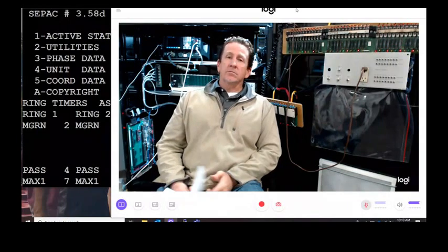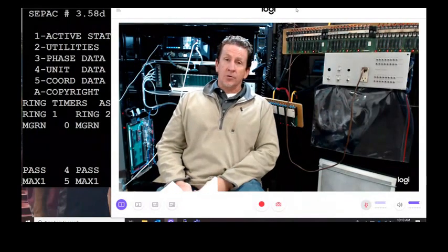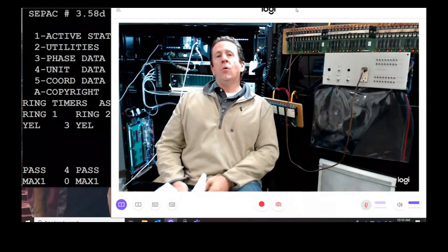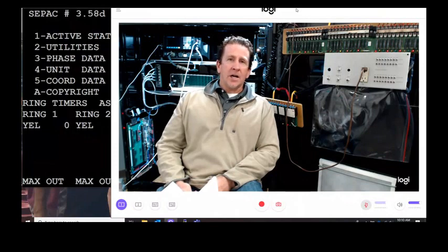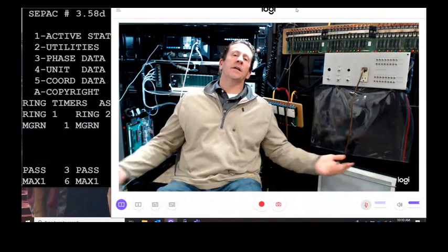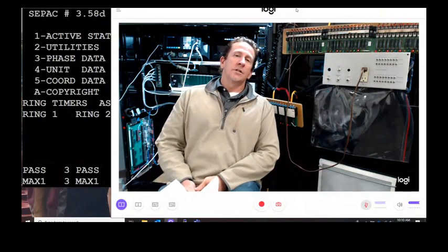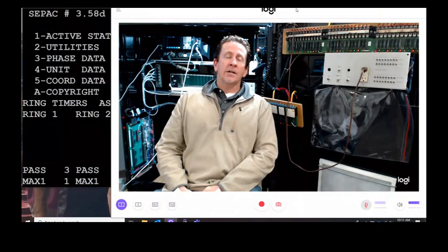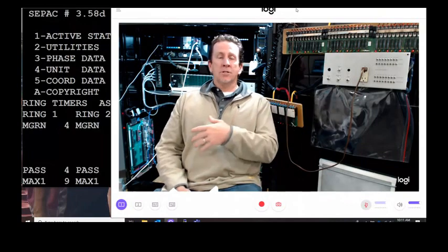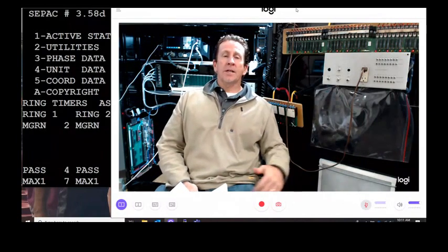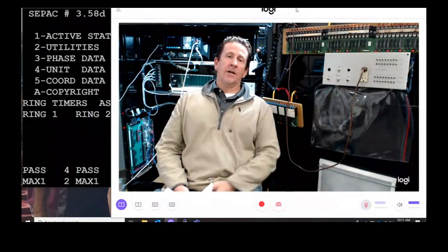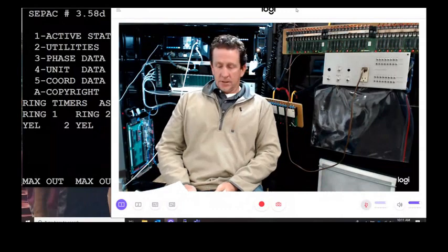Circuit breakers, it's like anything else. Most of you guys are all electricians. You know what a tripped circuit breaker looks like. We have our main breaker. We have 2 aux breakers. A lot of you guys tie auxiliary street lighting or Christmas tree lighting or some other kind of lighting that is powered out of our cabinets. So there's always the opportunity where something can trip a breaker in there. So when you come in, check out the breakers. They're right there. Sometimes you trip the breaker and that's what causes it to go into flash. You reset the breaker, it trips again. That now points you in the direction that it could be something auxiliary to the cabinet and not going on in the cabinet, depending on what you have tied into it.